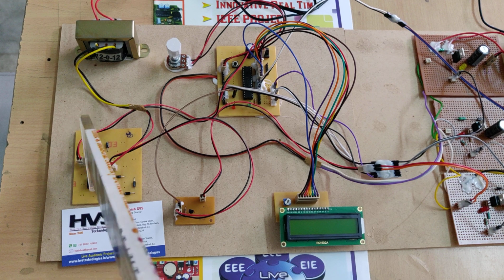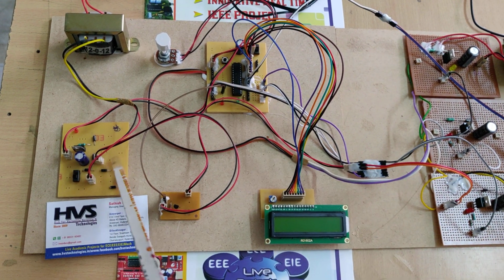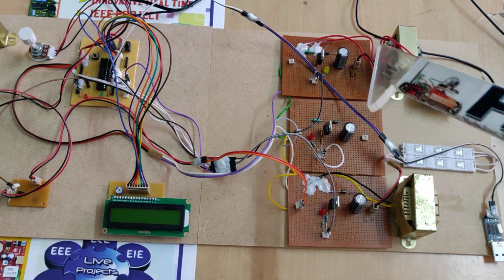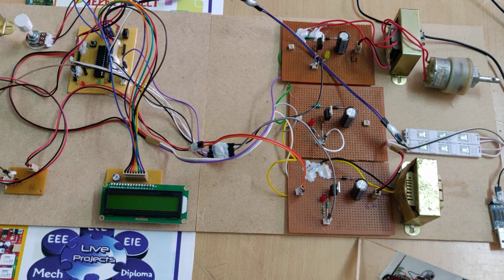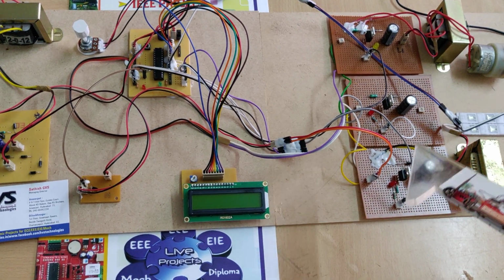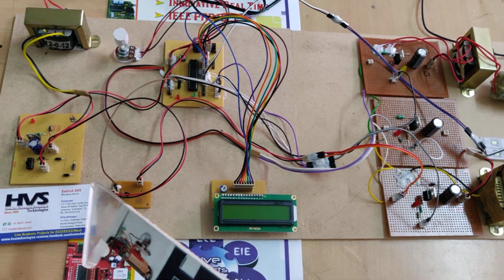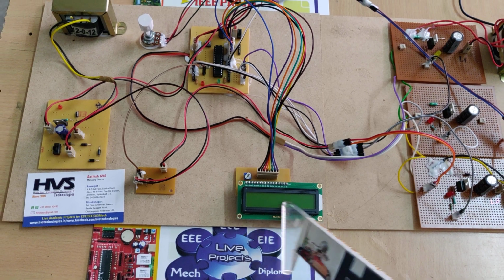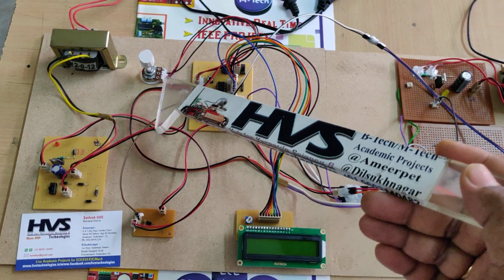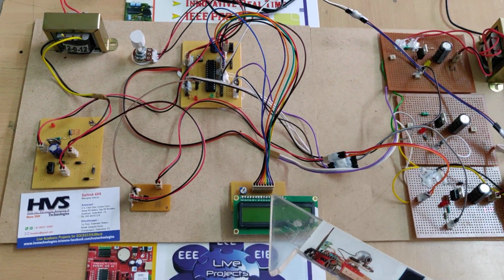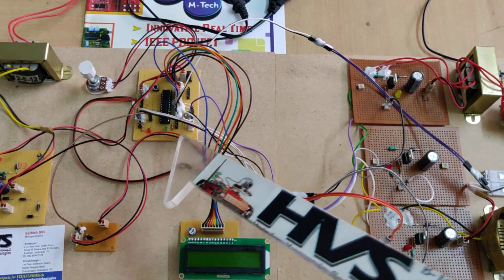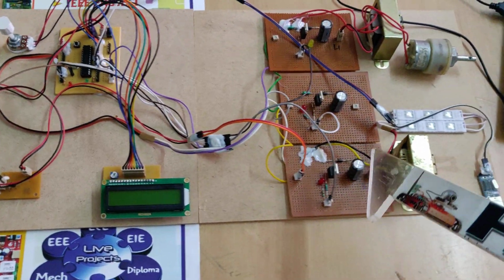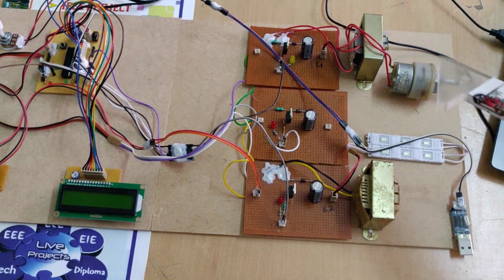So this 5 volts is the main input power supply to our PIC microcontroller, and this 12 volts DC is the main input power supply to our load through the buck, buck boost and boost converters. These are the three we are going to interleave in one project based on the input signal voltage that will be measured by our PIC microcontroller, and the status will be displayed on the LCD screen. We are going to change the input reference voltage with the help of a potentiometer, and based on that we control the pulse width modulation to these 3 MOSFETs, and we can regulate the output voltage to the loads also.